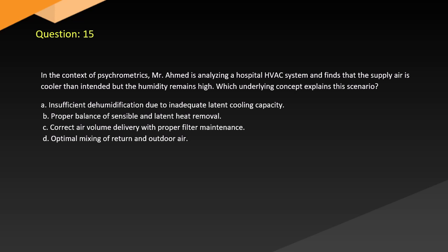Question 15. In the context of psychrometrics, Mr. Ahmed is analyzing a hospital HVAC system and finds that the supply air is cooler than intended but the humidity remains high. Which underlying concept explains this scenario? A. Insufficient dehumidification due to inadequate latent cooling capacity.